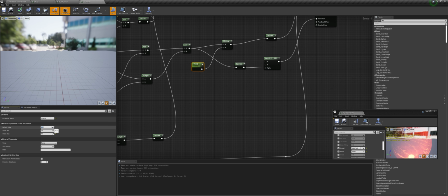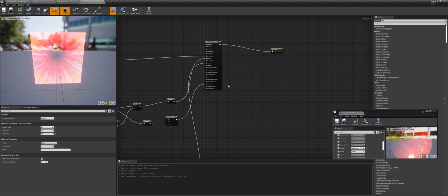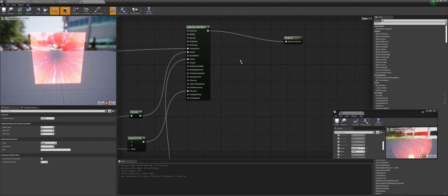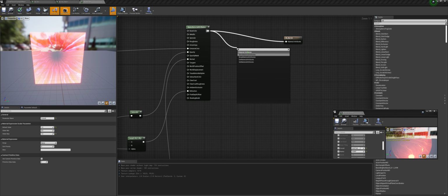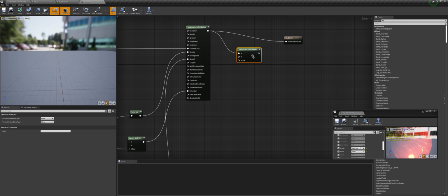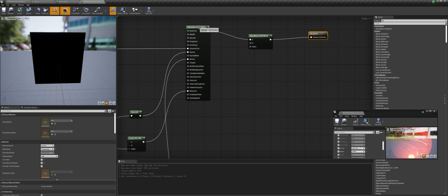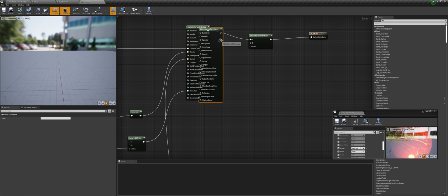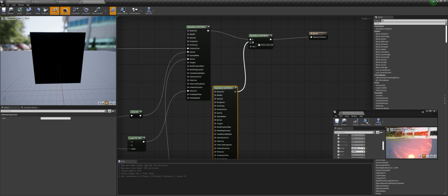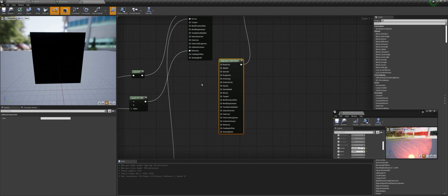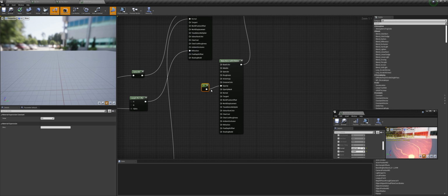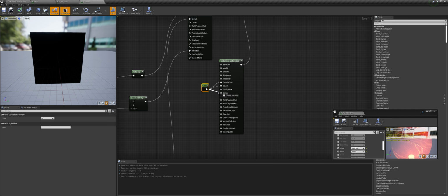So now we can set the overall value to like 1 here, so it will be visible. Now to lerp this on and off, we can get a blend node here, type in blend material attributes, then you can connect this here, and then we can just duplicate this and connect this to the B here, and here for the emissive, opacity, normal, and for the refraction we will give a value of 1.